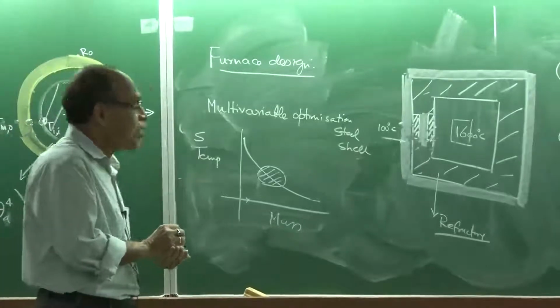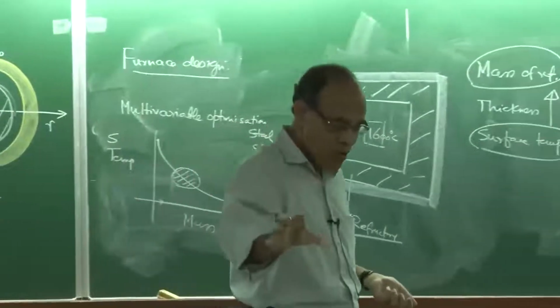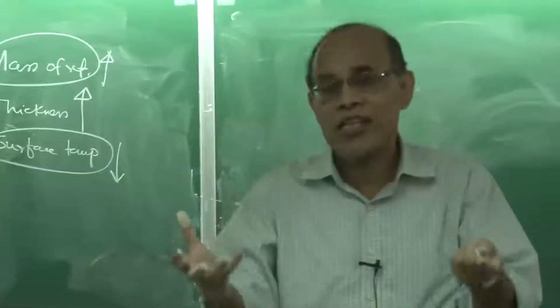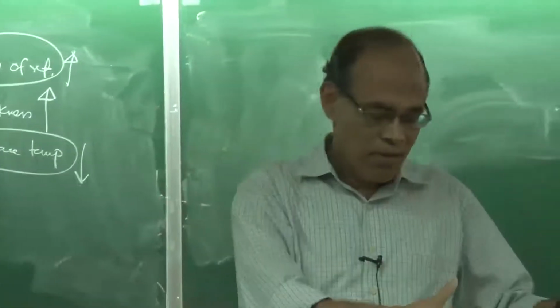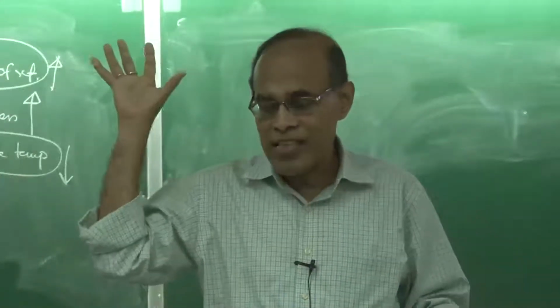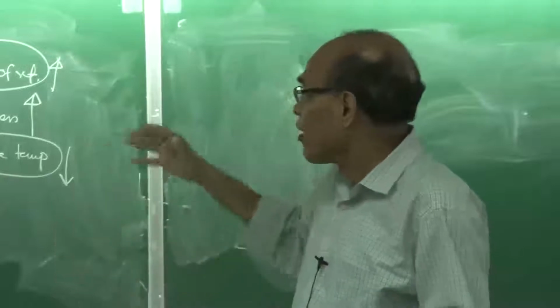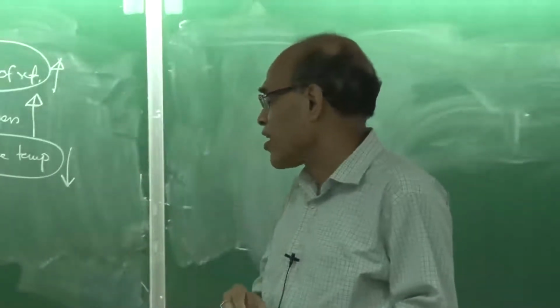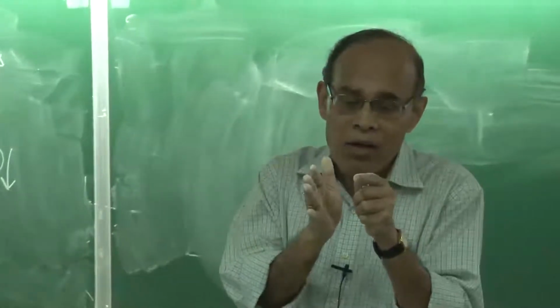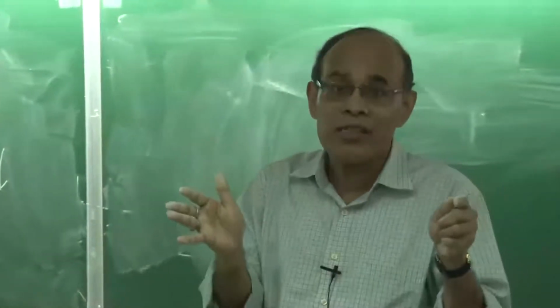Okay? So given brick materials to you, different brick materials, their thermal conductivities, and given an objective that for a given inside temperature a certain fixed outside temperature is desirable, one can work out by conduction heat transfer theories what the thickness of the refractory lining should be, whether they should be sandwiched or not, in order to fulfill the objective itself.